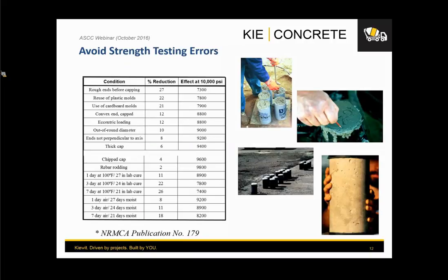Many people just think that cylinders are cylinders, right? You have the lowest guy in your operation, and you assign him to talking to the lab, and the guy doesn't know anything about concrete. He may know a little bit, and then you just say, hey, take some cylinders and put them there, right? Those cylinders are now exposed to a lot of things, right? The solar radiation, vibration in the field. Then people go and handle them at early age, and then they manage them. Some people may go and ride on top of them, do not put a cap on top to avoid having heavy operation, or just put them in the wrong curing conditions.